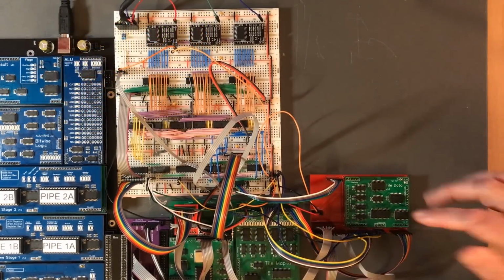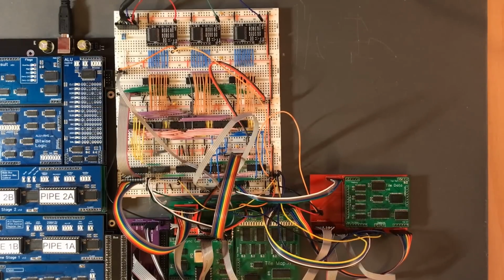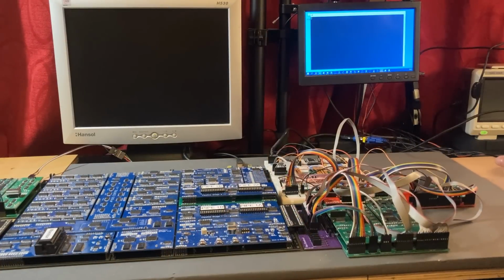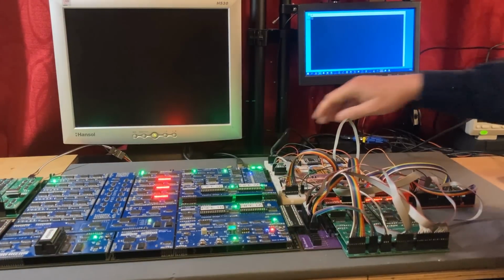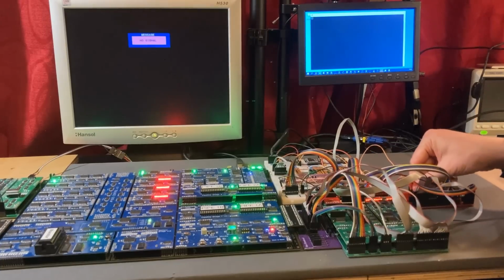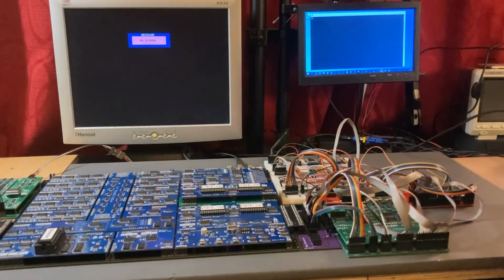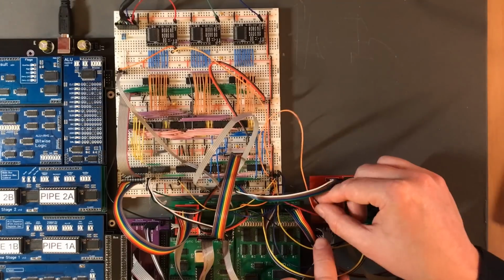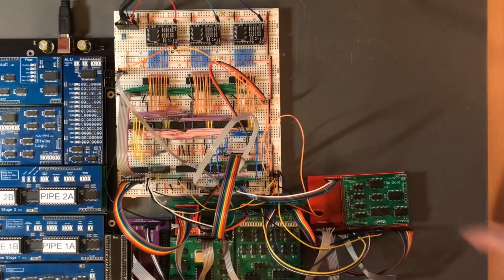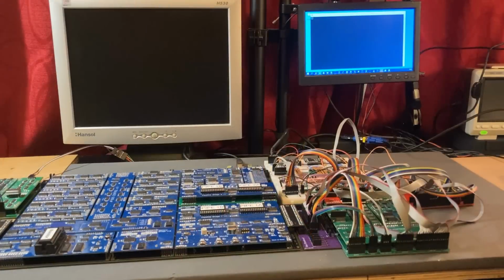Okay, well, nothing left to do now but try turning it on and hope it works. This is one of those times when I get to find out whether or not I'm quite close to the end of recording the video or whether or not I've got a whole bunch of diagnosis and possibly soldering to do. Okay, I don't like the look of that. We're not getting a VGA signal out. Right, let's power that down. That's a terribly bad start. Power and ground the wrong way round. Okay, let's hope we haven't blown anything up.